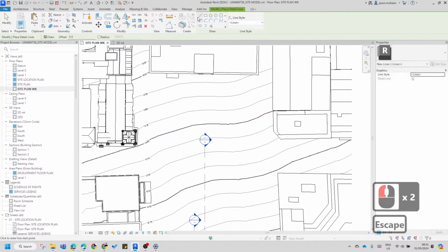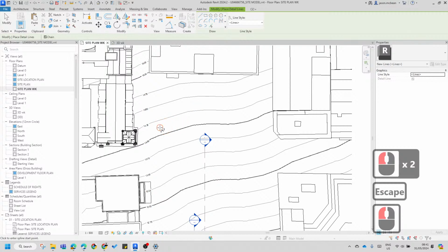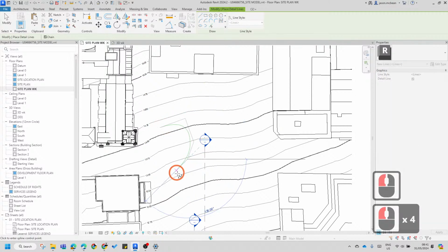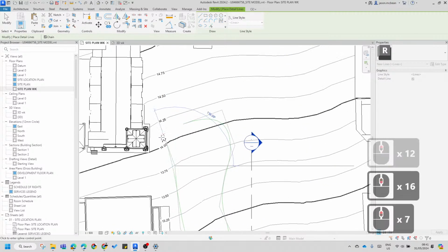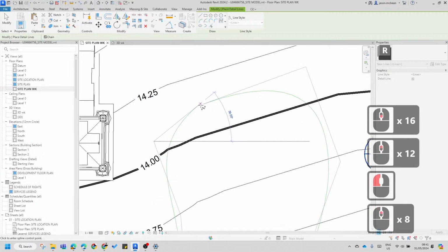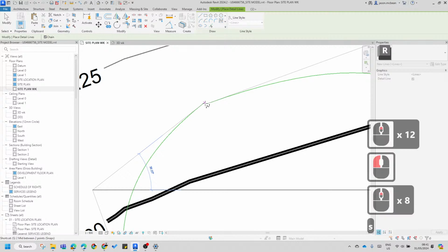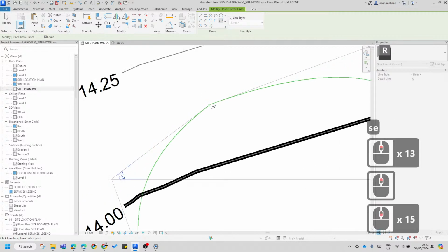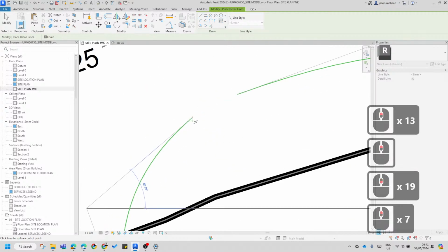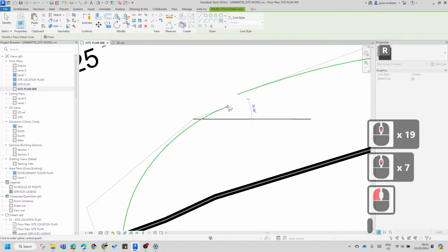Okay, so I'm going to create some very organic shapes. So say now I want to put these organic shapes like you did here. I'm just doing this rough. I'll come back and redo this again. This is quite interesting, but it doesn't like to close these things for some strange reason. Splines are not very snap end. You'll notice that these things they don't like to close splines. You need a straight bit of line work to close it, which I find interesting. Okay, enter.